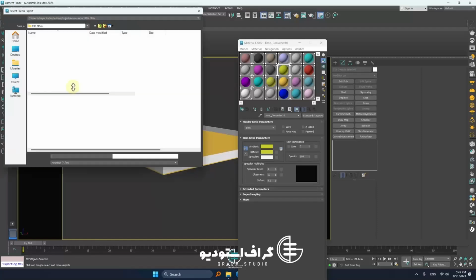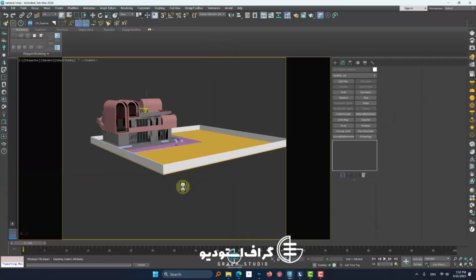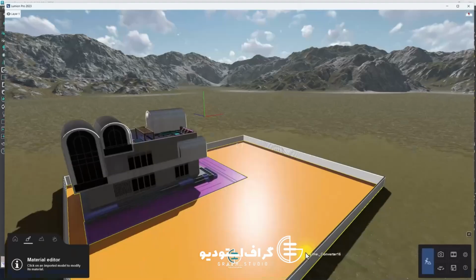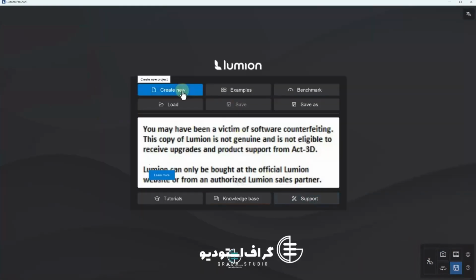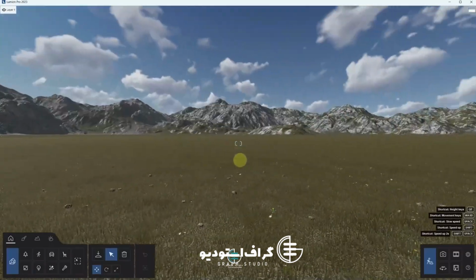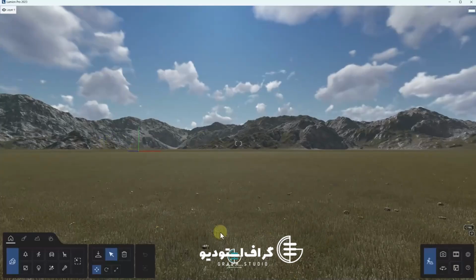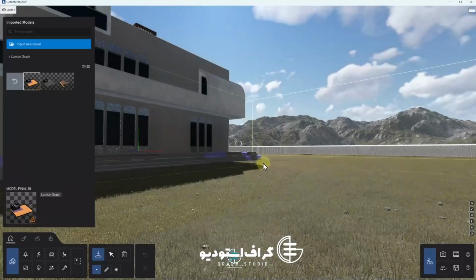The entire scene now uses the scanline material. Folks, even some of them had diffuse maps because we used the V-Ray mix exporter, and all of them, those with textures, gained a diffuse map. But since we didn't need it, I deleted their diffuse maps and only assigned a separate scanline material, named 14, 15, 16, and a distinct color, so we can separate them there. The scene is perfectly clean now. I even deleted a generator jack that was here, as Lumion has its own necessary decorative items internally.